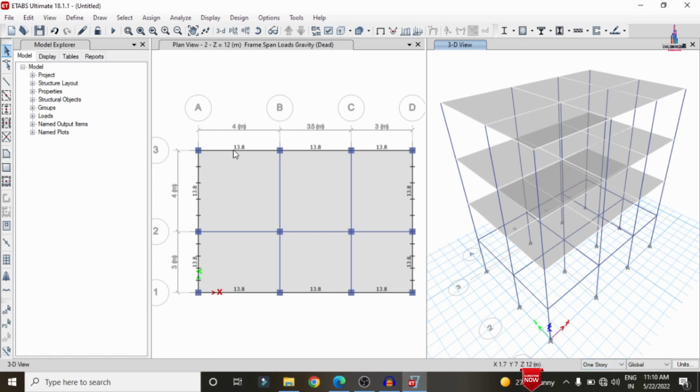Select this second view. So we have to select all the external wall loading conditions for the building structural consideration here. I am selecting here. Again I am selecting here. Again I am selecting here for the building. Go to click on the assign option, frame line load, distributed condition.